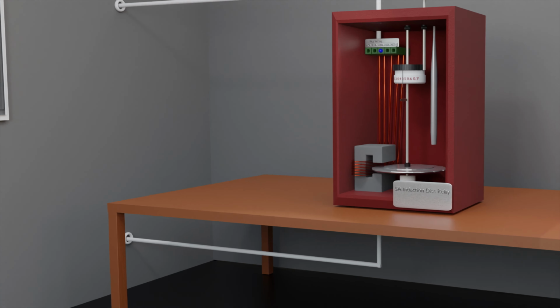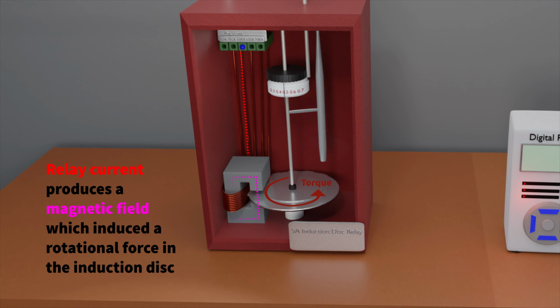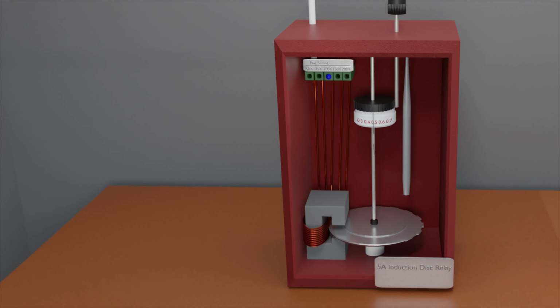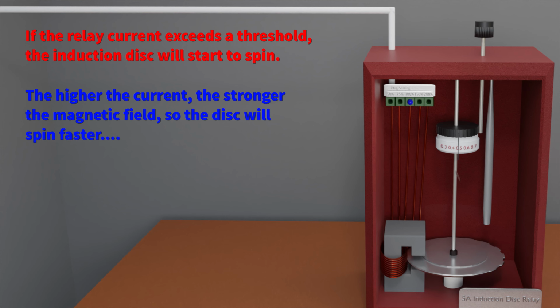The current through the relay has generated a magnetic field which induces a torque in an induction disc. The induction disc therefore rotates, and if it rotates far enough, a rotating arm hits a contact, and this initiates the instruction to the circuit breaker. Now, we don't want the breaker to operate under normal conditions, so there's a threshold beyond which the relay will operate. And the higher the fault current, the higher the relay current, and the stronger the deflecting force on the induction disc will be. So the relay will operate faster for higher fault currents.